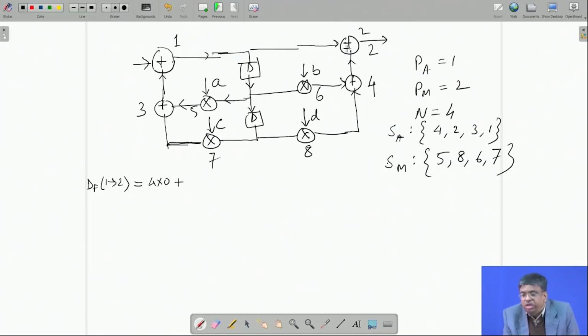Plus V, that is the schedule of node 2. Schedule of node 2 is 1, minus the schedule of node 1, node 1 is 3, so 3, minus the pipeline latch for adder which is 1. So, this is negative, minus 3. We want every edge delay to be positive, but here I am getting negative, minus 3. Fine, fair enough, let us still proceed.